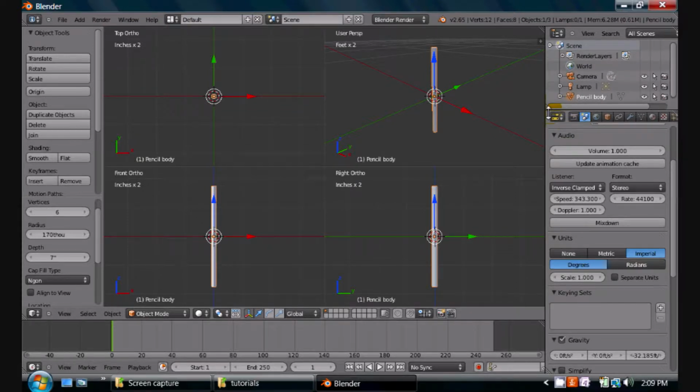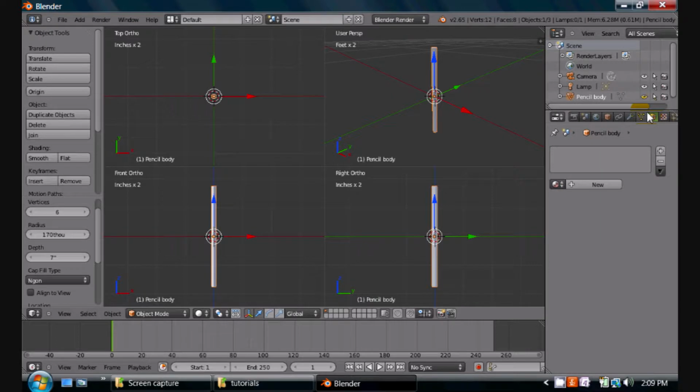Okay, so next we need to give this a material. So along the top here, instead of the scene button, we're going to come over here and hit the material button. And that gives us a pretty nondescript window, but it's powerful. The way this works is objects contain meshes, and meshes contain vertices and faces. All right, so this object, we're going to put some plugs into it, basically, so it'll accept some material parameters that we supply for it. I'm going to hit the white plug. There it goes. That actually gave us a couple.